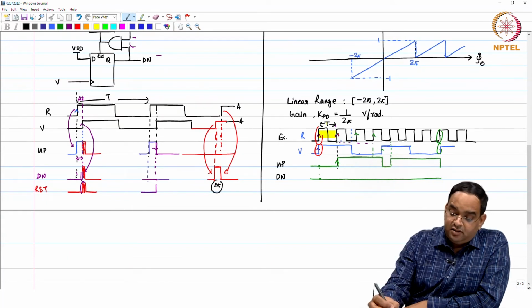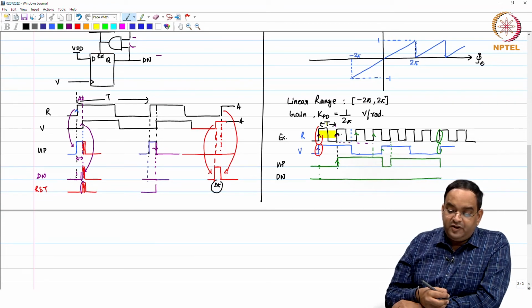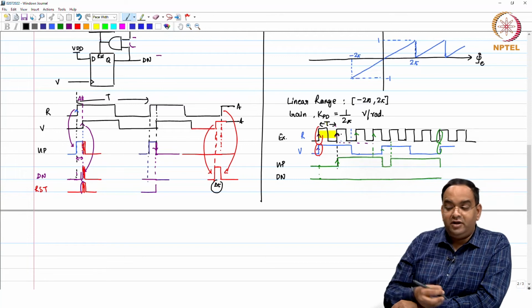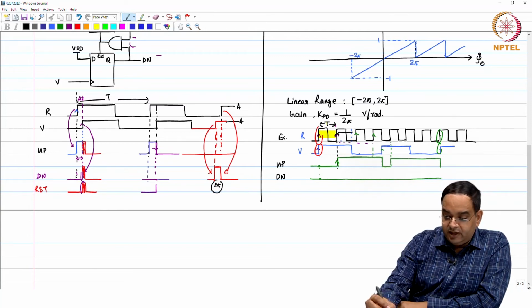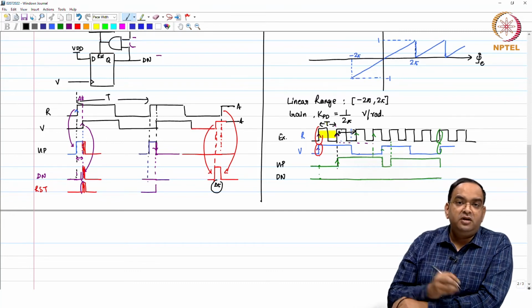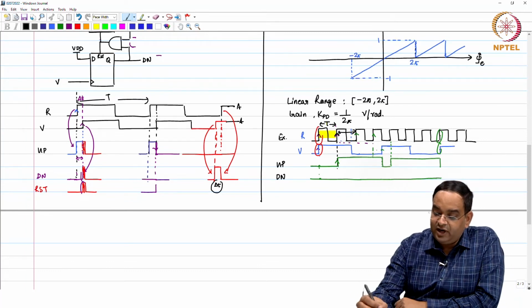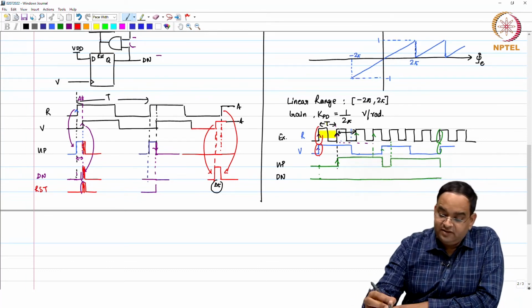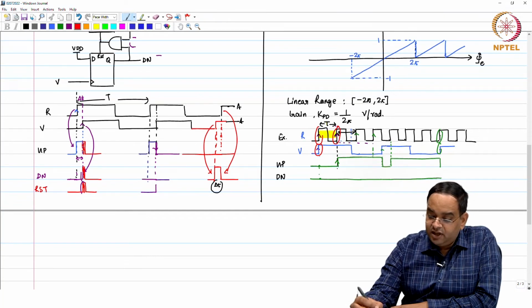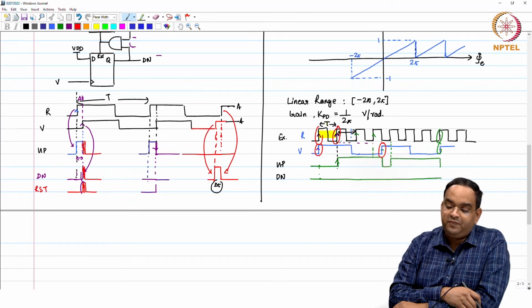And then if you look at the second rising edge on R, in this whole period, you do not find a rising edge of V. Okay. So, your error between the two rising edges, when you get this one and when you get here, is like 2.5 clock periods of T_V. This is your error.